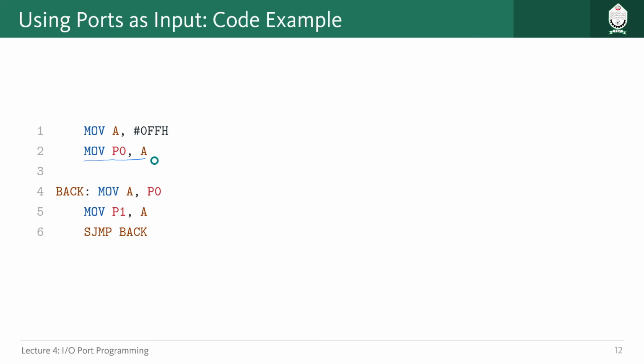In this line, it can look a bit confusing, but what is happening is after you have configured your port as input, whatever signal is connected externally to our port 0 will give us signals, 8 different signals, basically ones or zeros. That signal we will save onto our register A. So we are reading the pin, reading port 0.